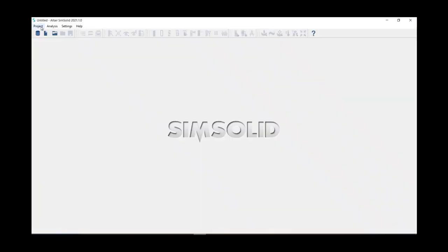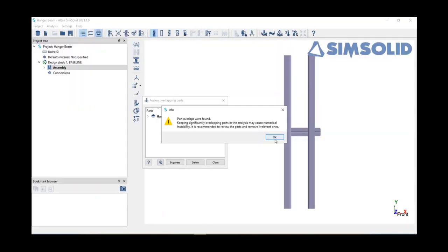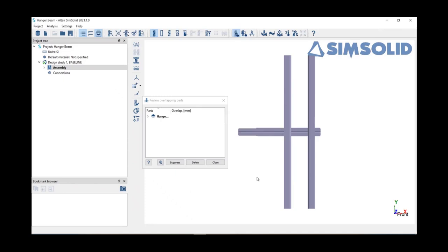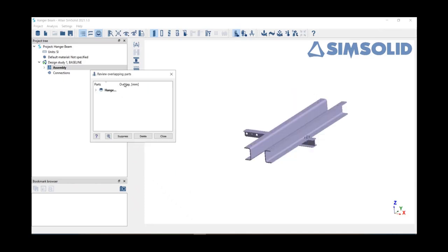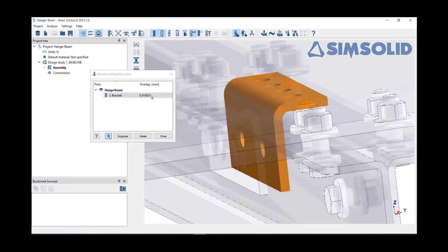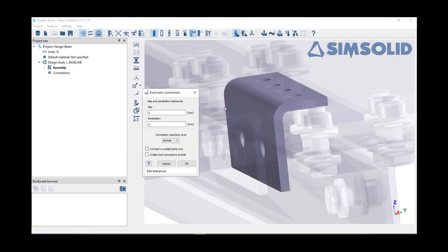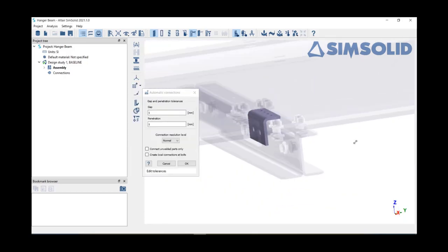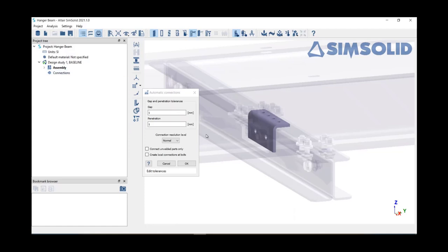And we will do this with a pretty simple beam model, well, a couple beams bolted together. Open this ParaSolid file. As always here, we see which parts have overlap. Always a good idea to zoom in there. This overlap is on the order of a fraction of a millimeter, and these are full-size bolted beams, so we're going to be able to handle that overlap without any real problems.